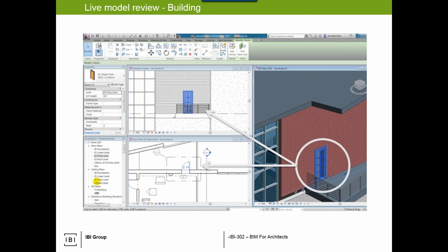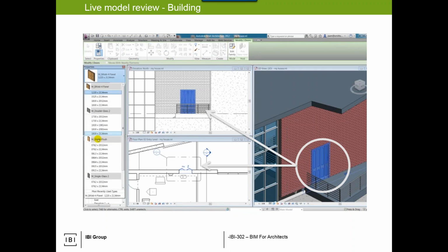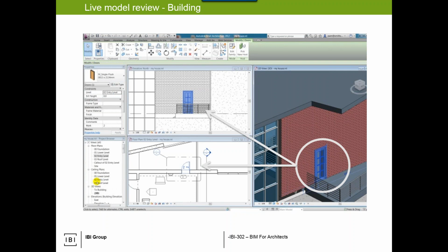So that happens a lot as well, and that's why I've noticed there's maybe lesser use of Navisworks than I would have thought, because oftentimes we're doing review just live in the Revit model itself. The drawback of this that you've got to be careful of is, as I'm changing this door here, if I delete it by mistake or set it to something wrong and sync it back, well, that's live on the project. So we've just got to be careful with that.